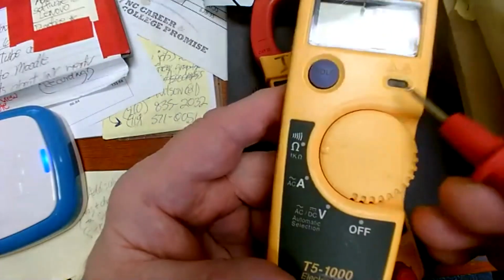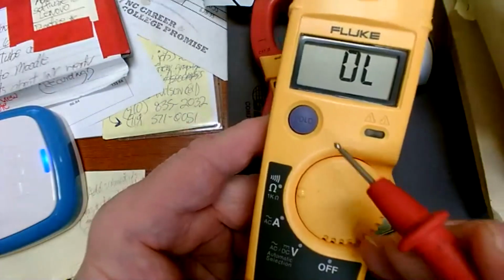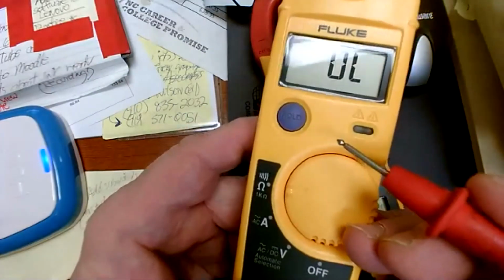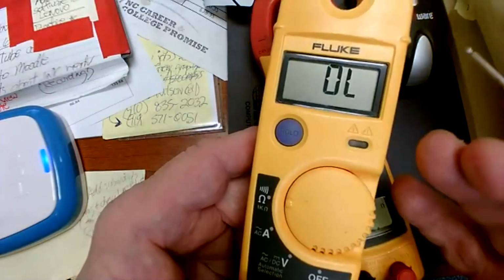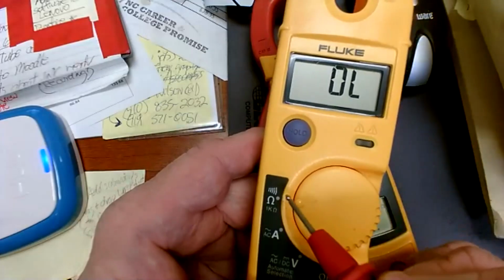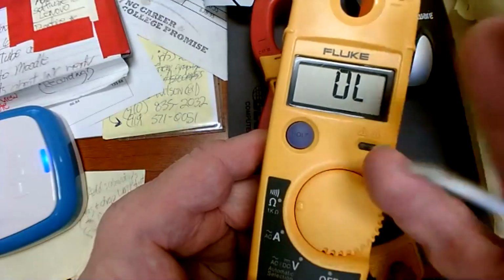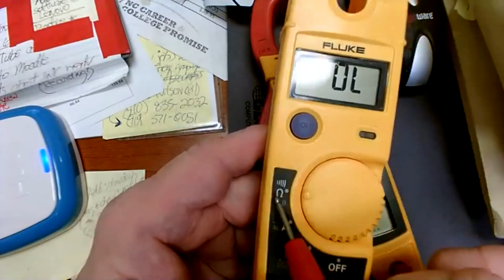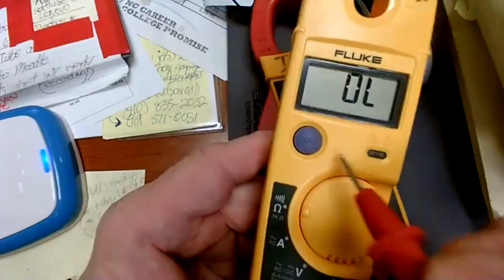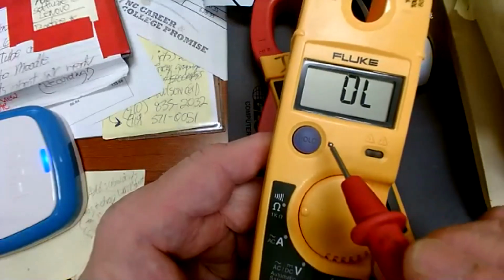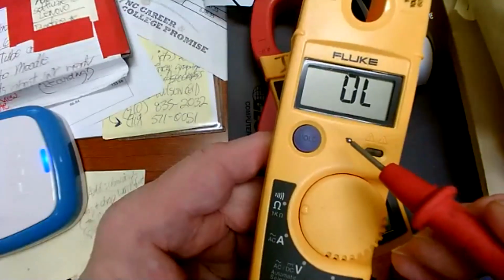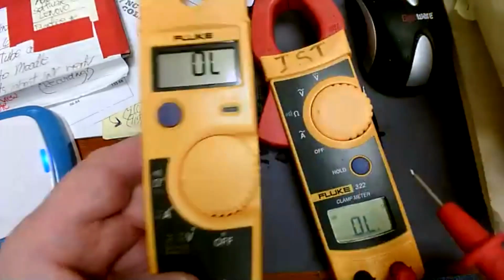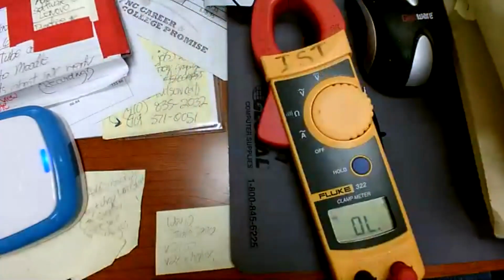So there are devices that would read higher than that when you're checking coils on relays and you're checking resistors in circuits and things like that. They can be well above that and nothing be wrong with them. But if you check a device that has more resistance than 1,000 ohms, this meter is going to tell you OL, and you may say that particular device is bad when it's not. So you've got to go up to a meter that has a higher range, okay?